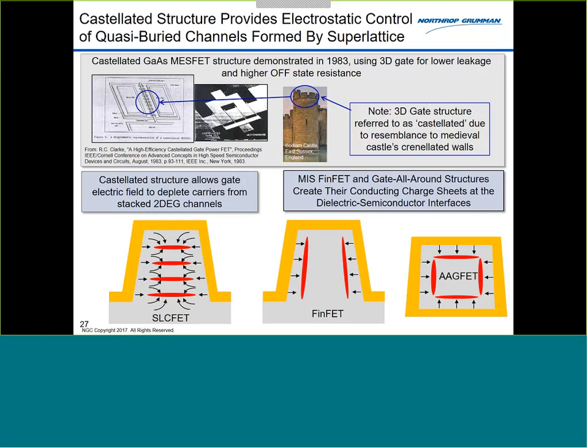And it's different from the FinFET. The SlickFET is distinct from that FinFET structure. On the left, of course, I show the SlickFET structure. A FinFET is notable, of course; that's very common in the silicon world, certainly in deep node devices. It's like a conventional device that's been corrugated, because it's still very much a surface channel device, where you're applying your field orthogonally to the device. So it does have some similarities in being a 3-dimensional gate. But what makes the SlickFET distinct is having that 3-dimensional gate, but then also applying the fields from those edges.